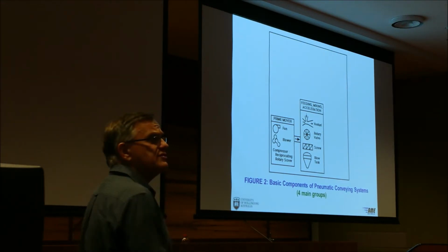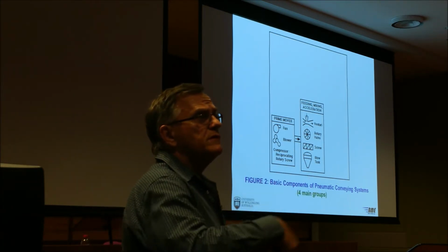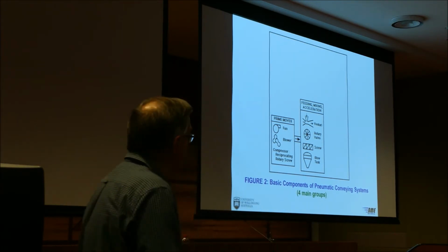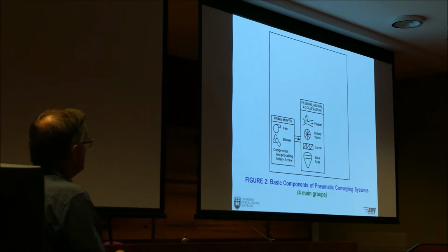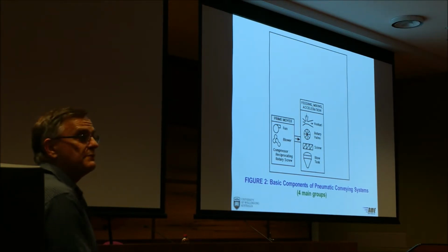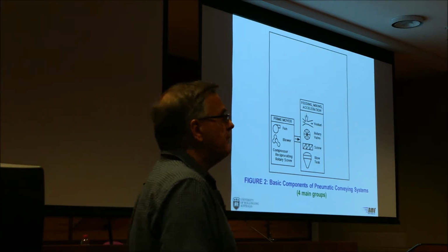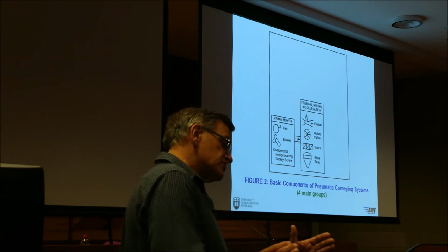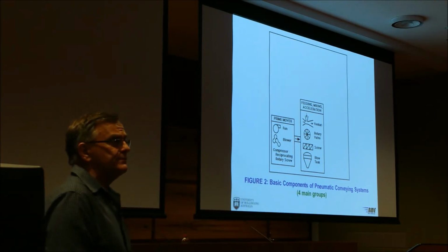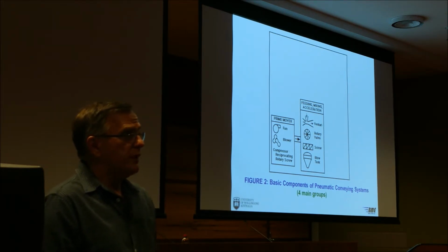Probably the most common feeder is the rotary valve. It's just a little volumetric feeder. You want more product in your line, just increase the speed. So I'll show you examples a bit later on. Then you can feed powders or granules with the rotary valve. Screw pumps are generally for powders, like cement. And the screw actually has a decreasing pitch, which compresses the powder inside the casing to form the pressure seal. And these devices can go up to 200 to 300 kilopascal operating pressure.